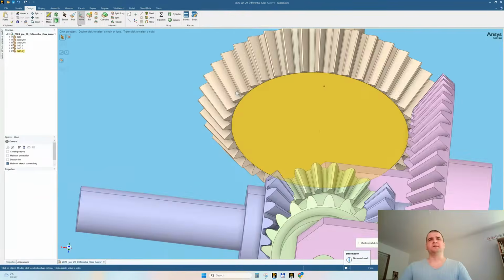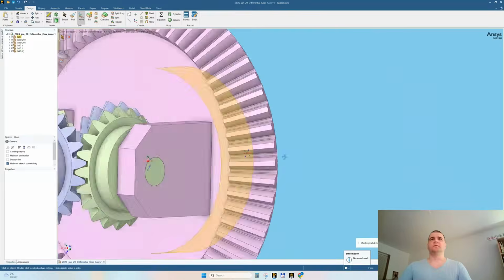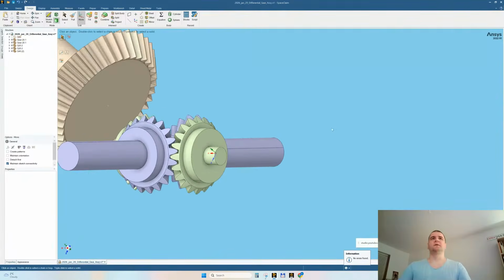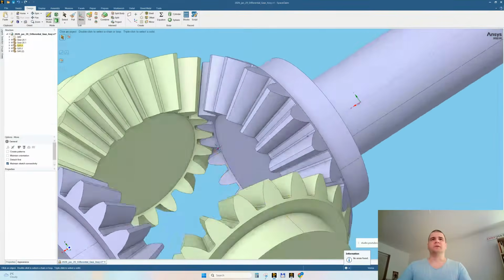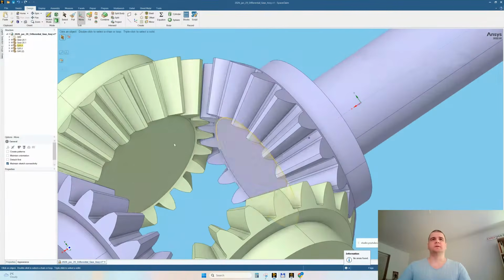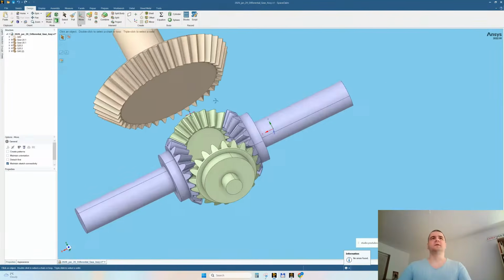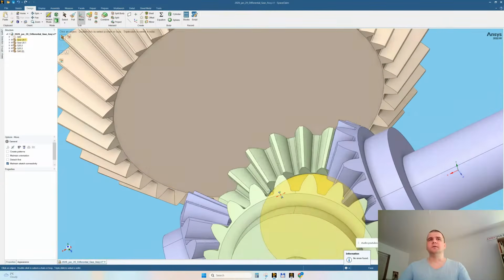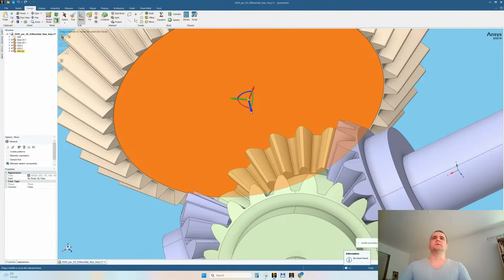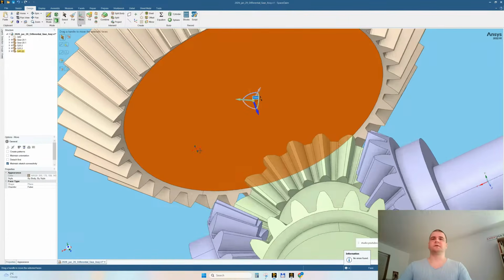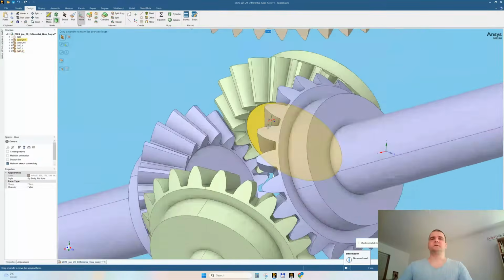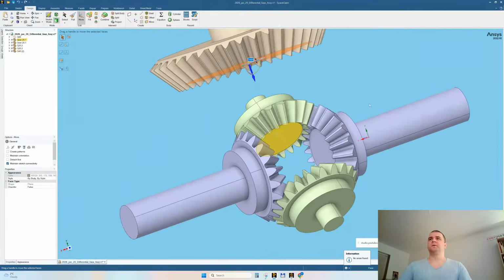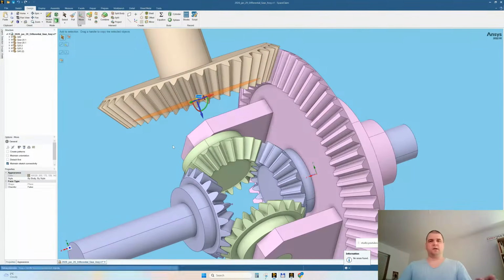I'm thinking about the element size that will be here. Let's hide this. Where will we have small elements? Here. Yeah, let's leave it like this. I kind of wanted maybe. Yeah, let's push this a little. Something like this. 1 millimeter. To have bigger elements here, yes. We don't need to torture ourselves with so fine mesh. Show all, save.